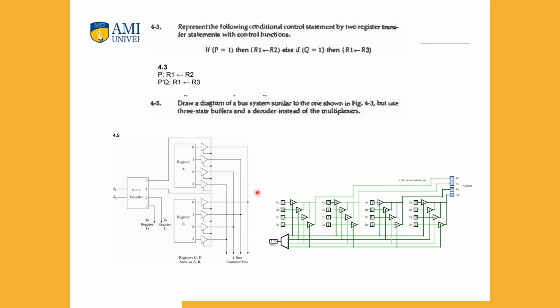system accordingly. So you have register A connected to 4 tri-state buffers. Each of them are given the same decoder line. So if the selection is 0 0, then each of the tri-state buffers will be having one value transferring, and hence it will allow the A bit transfer. Similarly, in the second row of tri-state buffers, we have the B bits. The register B is connected, and we give them the same line, the second line of the decoder, in each of them, and so on.